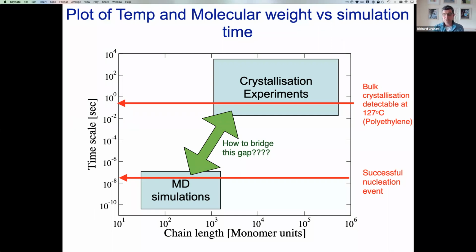In a lab situation, it's more typically done in a rheometer, which is a machine to impose a well-controlled flow, typically shear. So a sort of idealized picture of how they do that, if you can see me on the video, is you have two plates and you hold one plate fixed, then you just use a force to drive the plate that way to impose the flow, shear flow. Mostly the shear rheometers do it in a circular arrangement so that you don't run out of space. So there you're using a stress to drive the top plate, and then the internal structure of the fluid spreads that flow through between the plates.